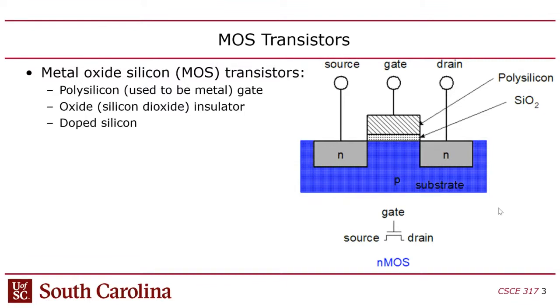So this gives you a MOSFET transistor, and it basically gives you 4 terminals. There's the gate, which is in the middle, and then there's the source and the drain, and then there's the bulk terminal, which is the substrate. Even though you typically see a transistor depicted with only 3 terminals, the 4th terminal is wildly important. It's just usually not shown because it's usually implicit. But if you don't hook up the 4th terminal right, your chip is going to fry. And it will release the magic smoke, as Charles would say. So the 4th terminal is super important.